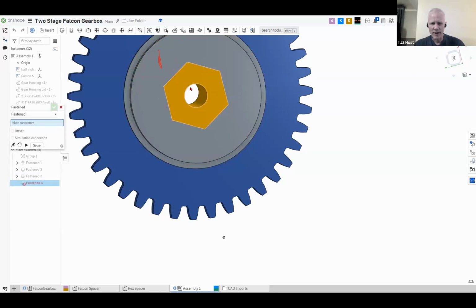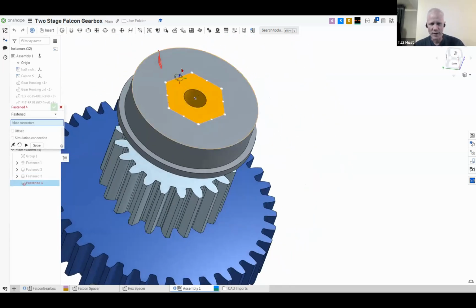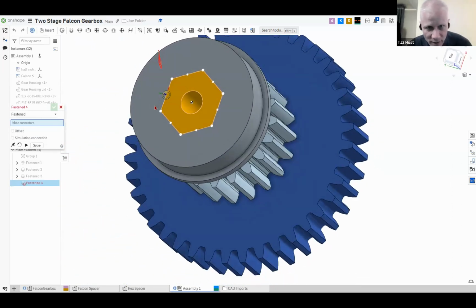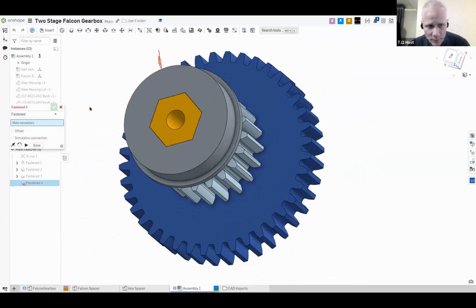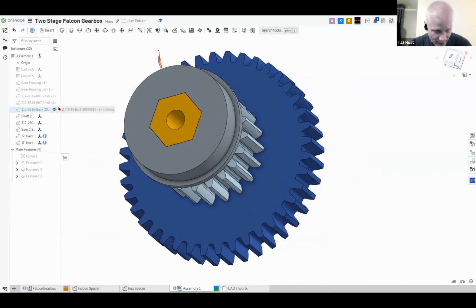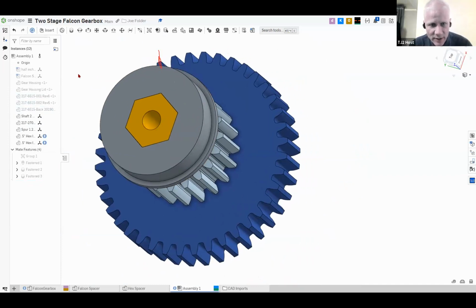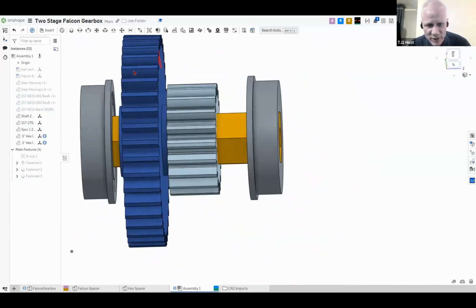So now, what I'd like you to do is we have a shaft, we're not quite done yet. So click OK, or X, because we're done mating. But there was a spacer we want to fit. Can you give me a side view or something so I can see the shaft? We want to fill this thing with a spacer, and we want to fill this thing with a spacer. So let's find out how big our spacers need to be by just touching this surface and then touching that surface and seeing how long our spacer should be. Do you understand what I mean by that?